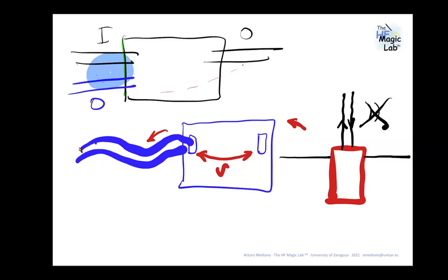Next up, aren't there impacts on the disturbances due to the fan? The fan can have an effect in two ways. The first is that the cable that is powering the fan is not filtered. And the second is that the fan is the load of the DC-DC converter and can make the DC-DC converter work in some specific way or another. So yes, the load of the DC-DC converter can have an effect on the emissions from the DC-DC converter.